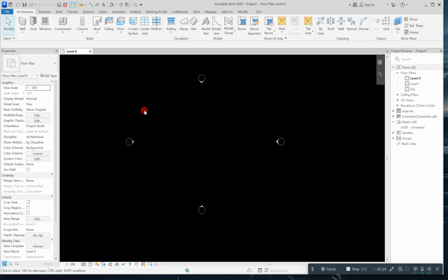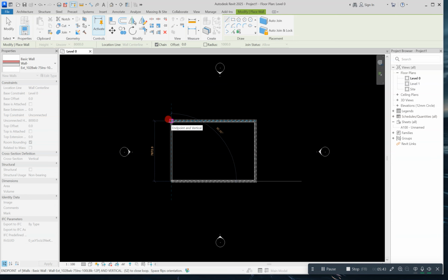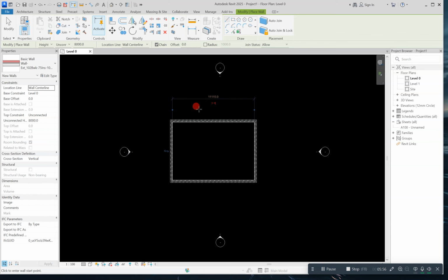Then the other thing that you have to set before you start any project are the units. The purpose being that it will be very hard for you to know, or you might end up putting wrong units as you're drafting or modeling. You see, when you're modeling, there are units that are indicated there on the default dimensions or temporary dimensions. So if at all you don't know the units you're working in, you might end up producing an inaccurate drawing. So it is better if you set your project units.